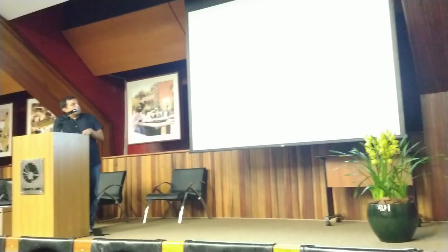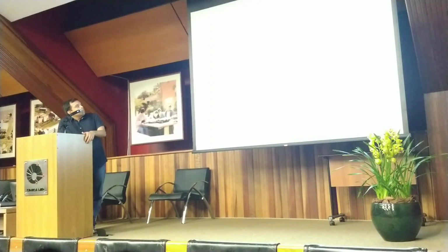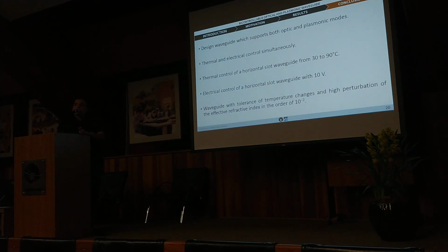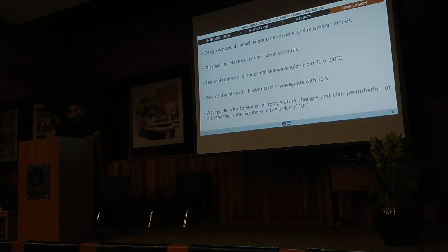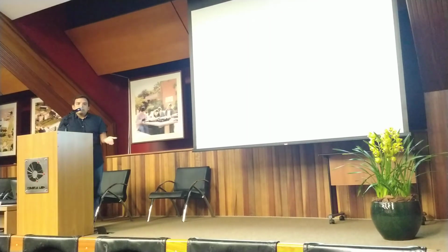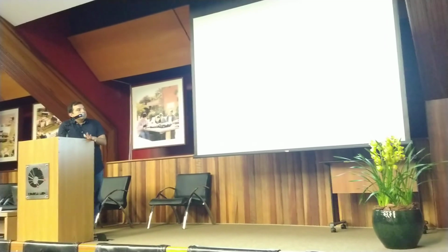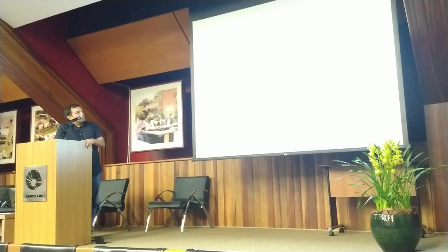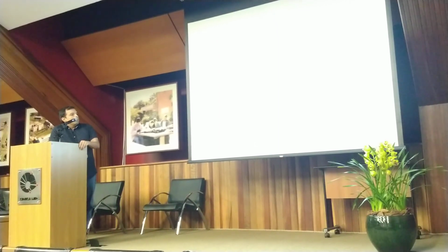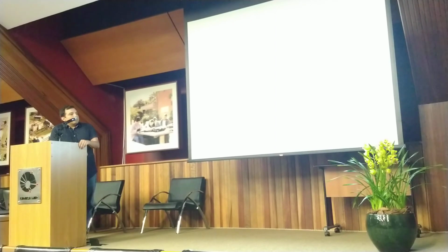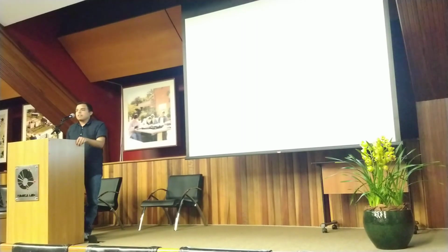To finalize my presentation, I want to present my conclusion. In this work, we designed a waveguide which supports both optical and plasmonic modes. We also present thermal and electrical control simultaneously, so we can change the thermal and the electrical control at the same time. We have a control of the waveguide from 10 to 90 degrees Celsius, and electrical control with 10 volts applied to the electrodes of the waveguide, and a high change in the effective index of the mode in the order of 10 to the minus 2. Thank you.